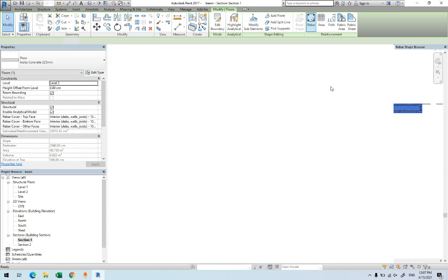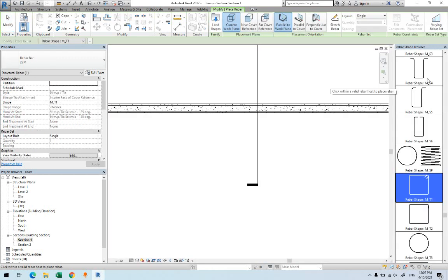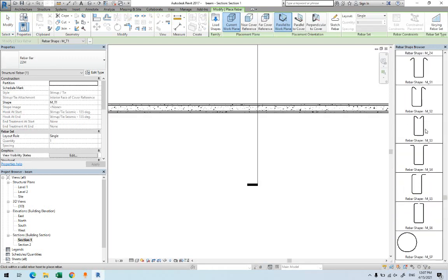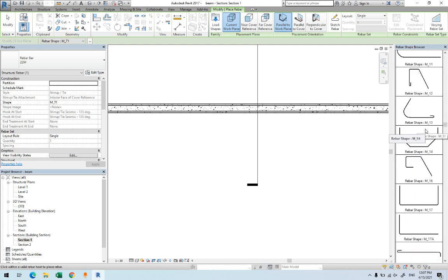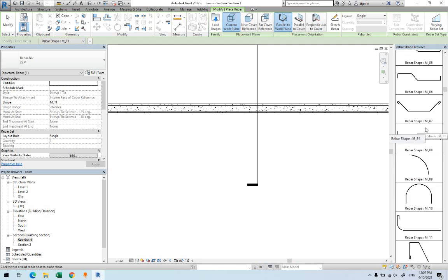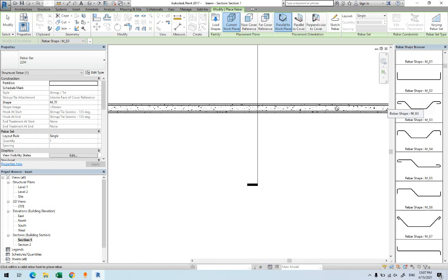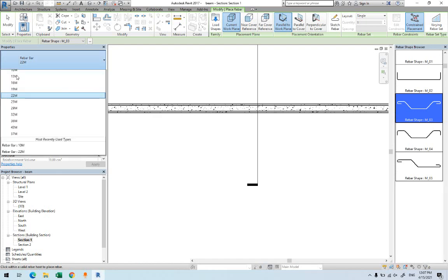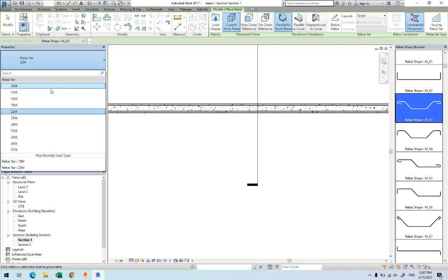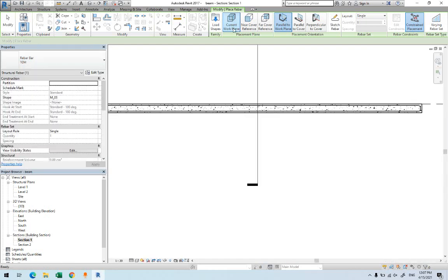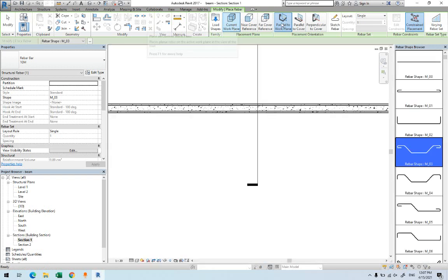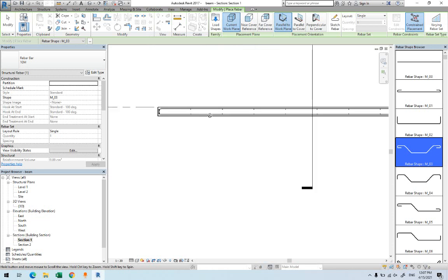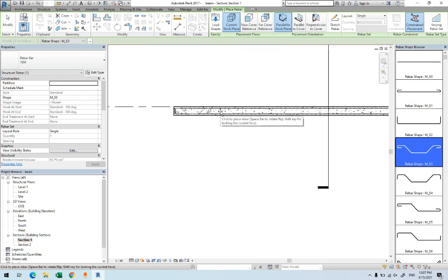Now in the rebar, you still have the same options that you could do, whether sketching or providing from this rebar shape. So you will come inside here. Let me change the bar size to 10. Then we are in the current work plane because of the section and parallel to work plane. So you realize that it will be provided here, yes? Look at the bar, I have it here.